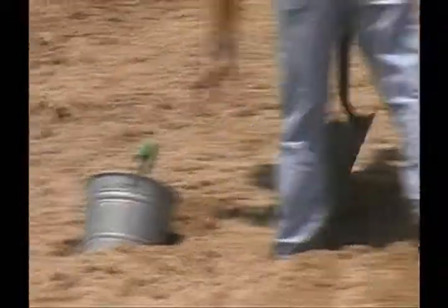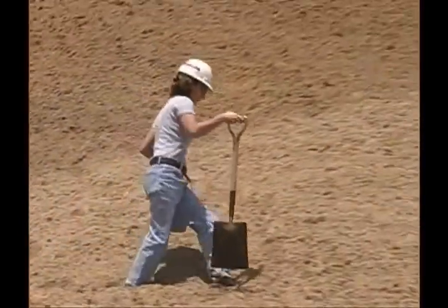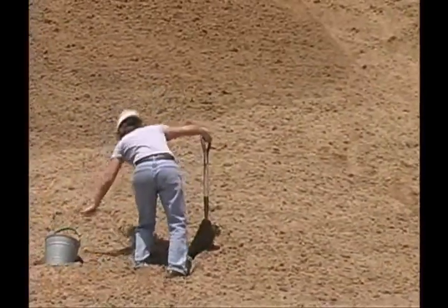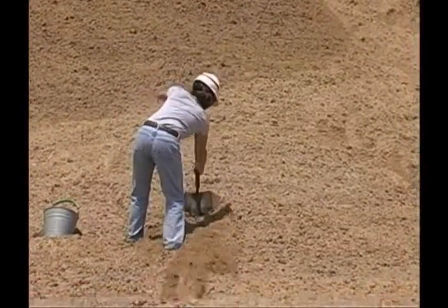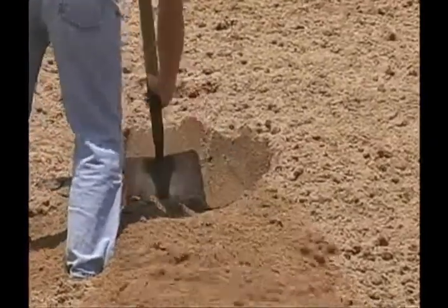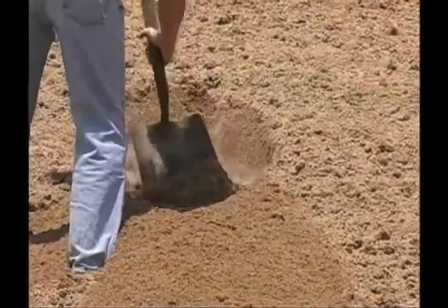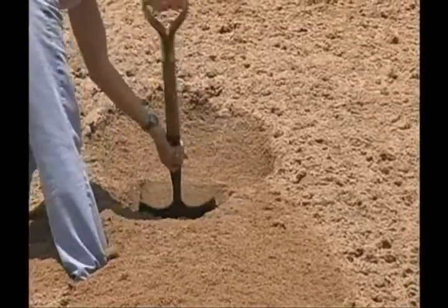and place the sampled material in a clean container. Move to another location around the stockpile and take another increment. Continue to sample in this method at least 3 times. Avoid sampling under the conveyor belt because this area usually contains fines. More increments may be necessary to get the minimum sample size.